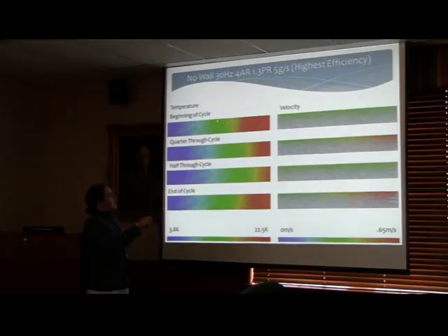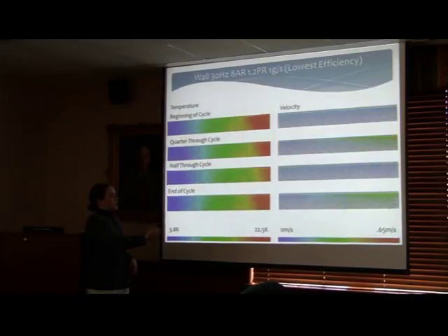So as you can see, this area of the pulse tube never leaves the pulse tube, and that's basically your gas piston. Now this was from our most efficient case. These are images from our most efficient case, and compared to our lowest efficient case, you can see that the velocity flow is much lower, and the flow is a little bit more unstable.